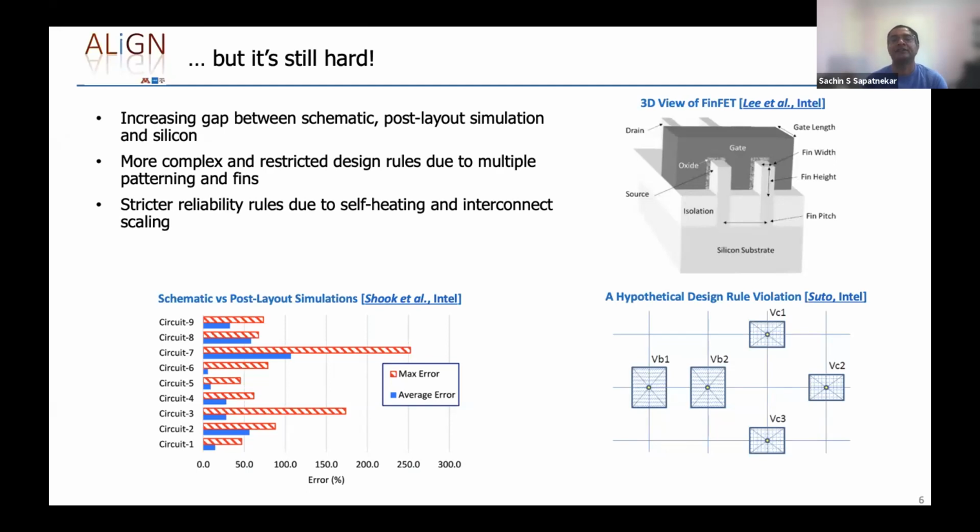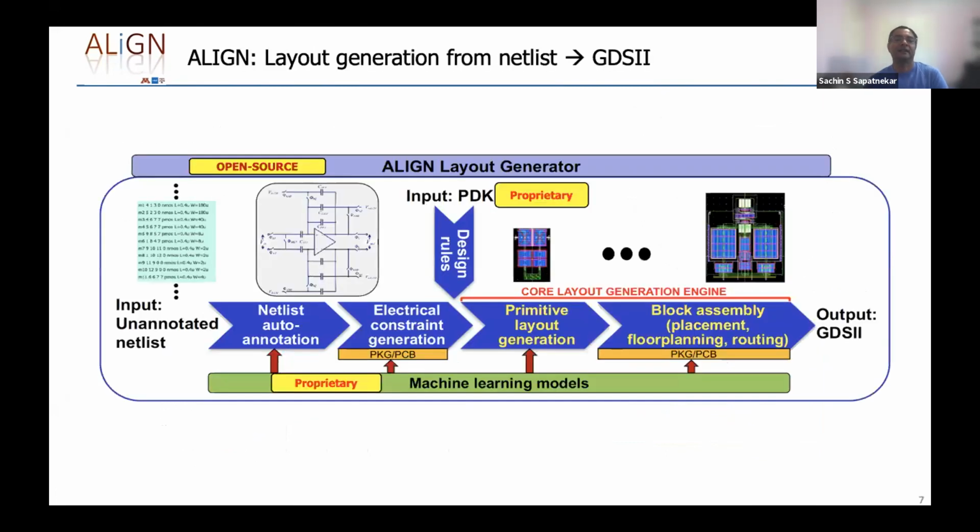So as a result of this, things become pretty complicated, because in order to maintain performance, you need to make sure that wire resistance is not a bottleneck. In many cases, we find that to meet performance, we need to use multiple parallel wires in lieu of wider wires because of pitch requirements, especially in lower metal layers. So that's the motivation.